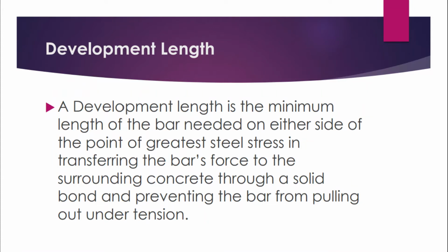Development length. A development length is the minimum length of the bar needed on either side of the point of greatest steel stress in transferring the bar's force to the surrounding concrete through a solid bond and preventing the bar from pulling out under tension.